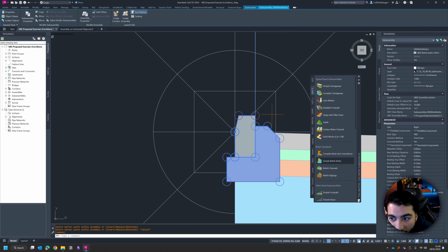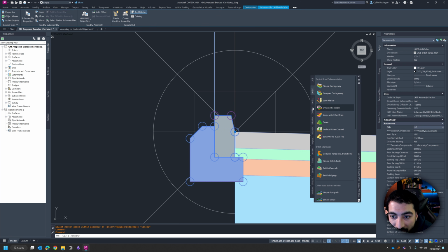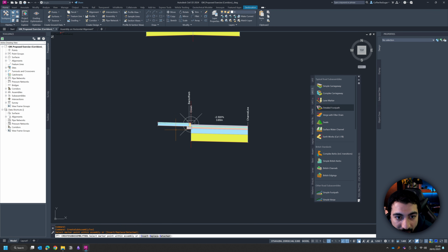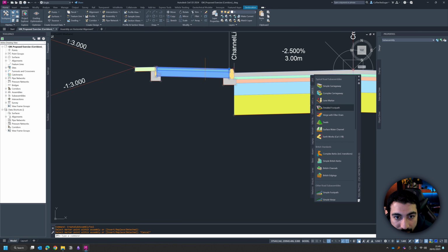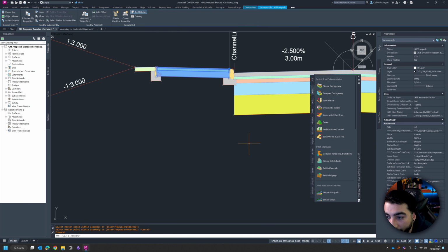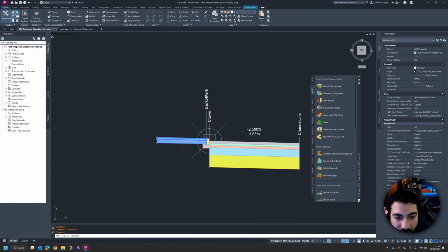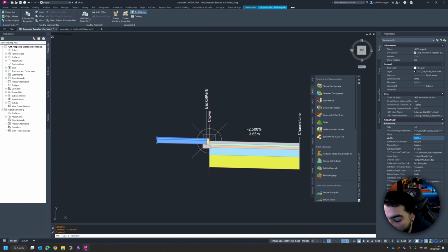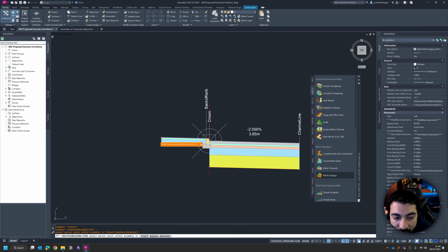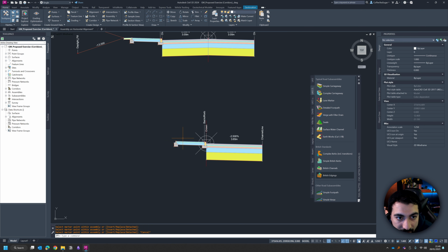Let's click on the curb, and then on the left hand side in the properties panel, detail footpath. Let's have a look. What was our footpath? Our footpath was 1.825 because we also had the edging. So let's do 1.825. Add our edging. And did I have a verge?